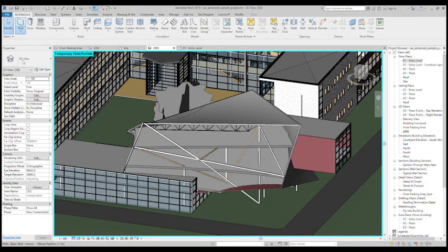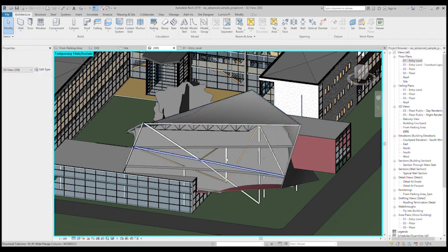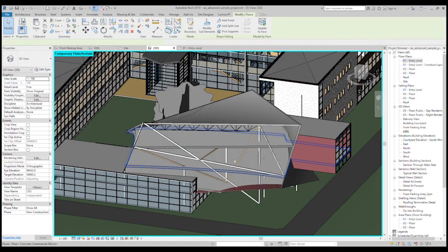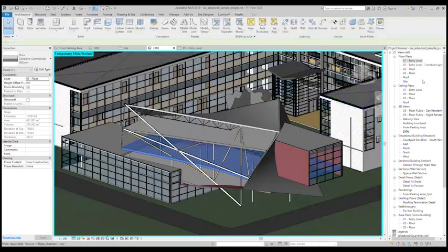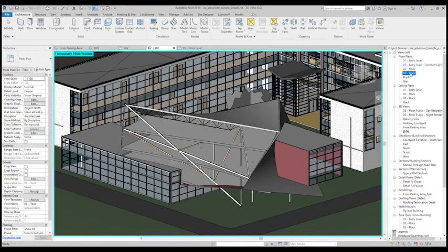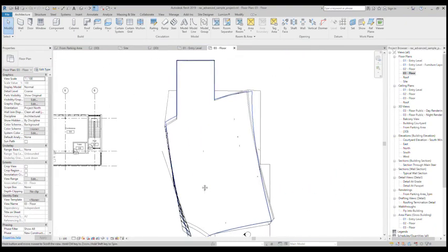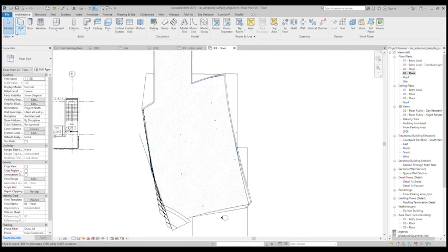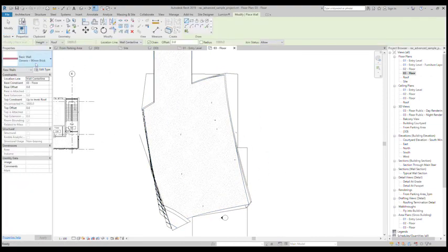Like we've drawn walls by face, you can always just draw walls in plan, which is called architectural walls. Okay. So I know that is level, the parapet roof level, or let's draw on that level, the third floor. I'm going to go to my third floor plan. There's my floor slab. Obviously you guys can see it. So I'm going to go to wall, architectural, and I'm going to draw it more or less.